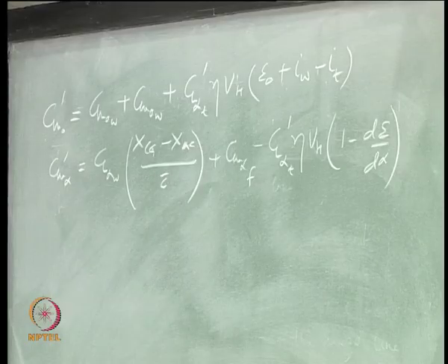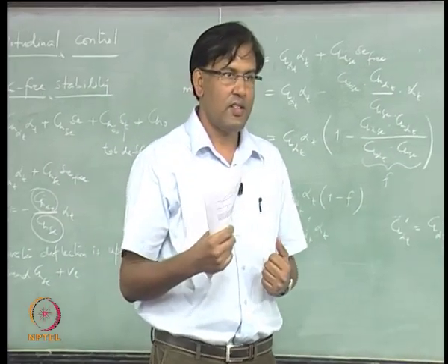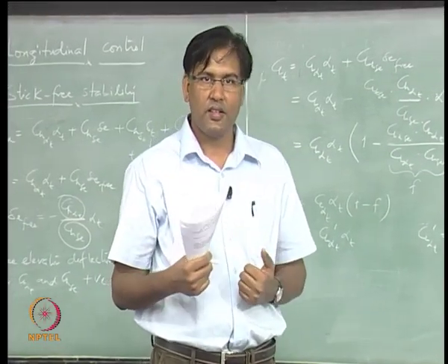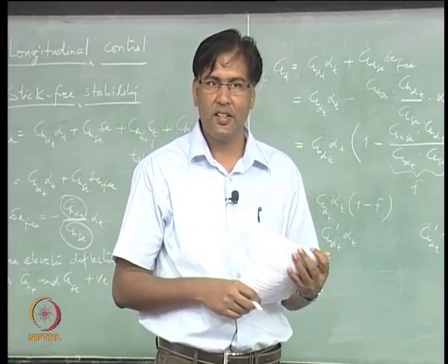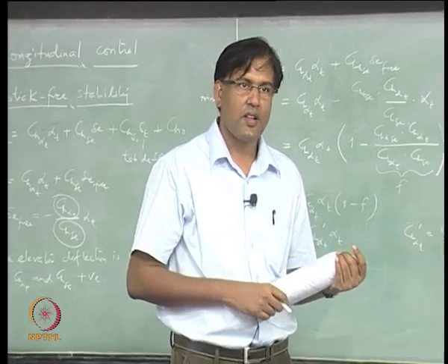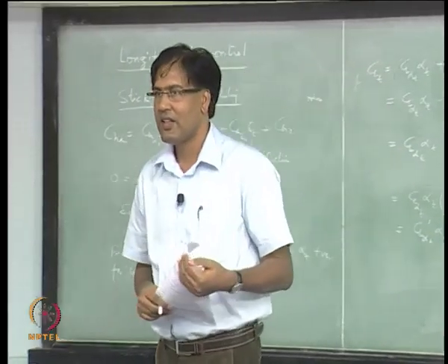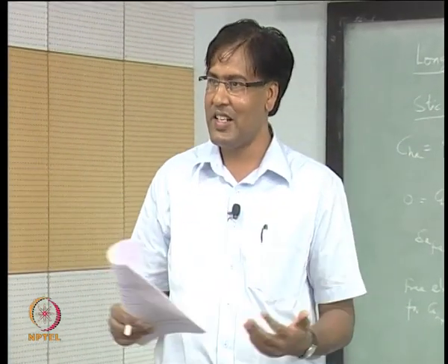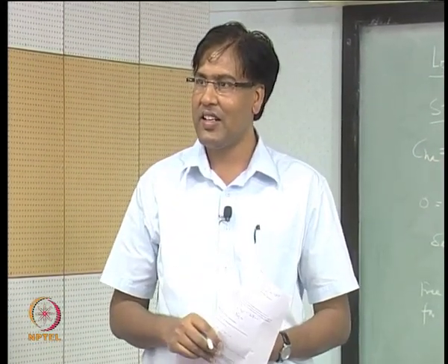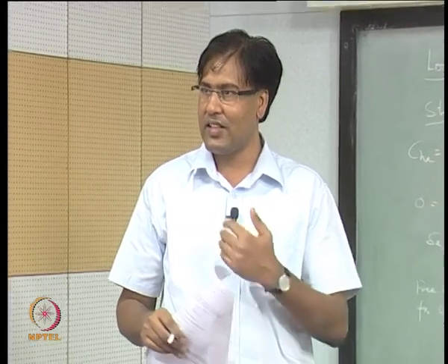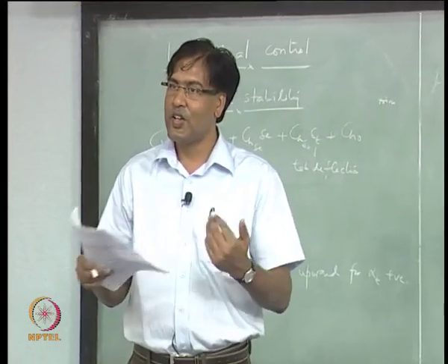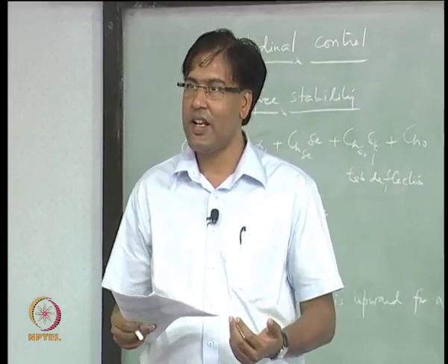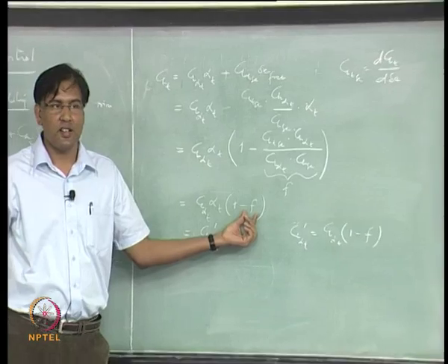Okay. So, I am going to see a change in what? There is something which is changing now, right. What is that? Cm alpha is changing, so static margin is changing, right, stability margin is changing, right, and that automatically implies that the neutral point location is changing, right. Which way? It will depend upon what this f is, right.